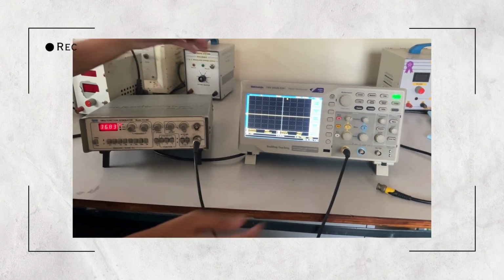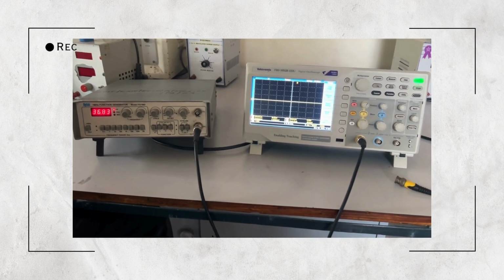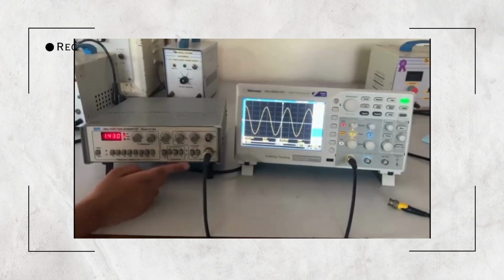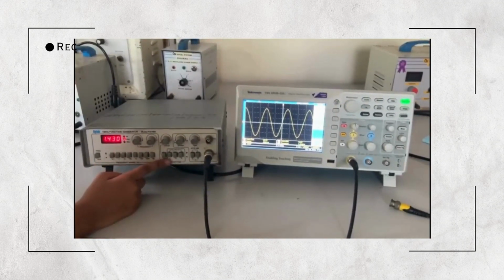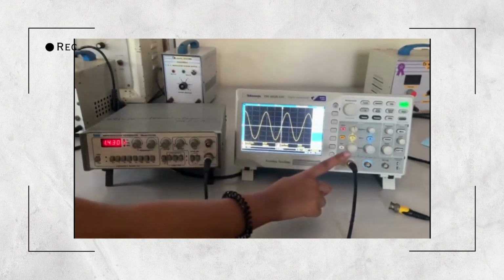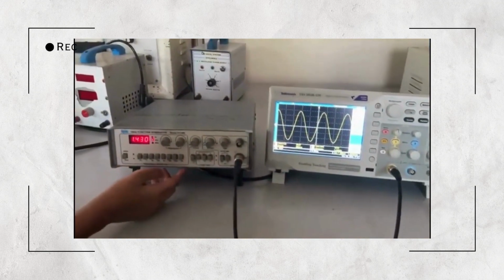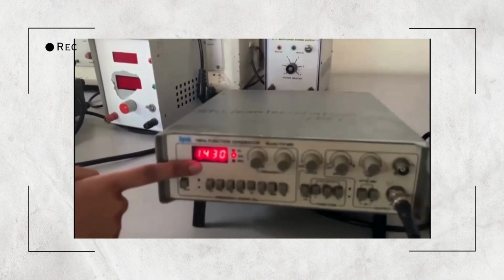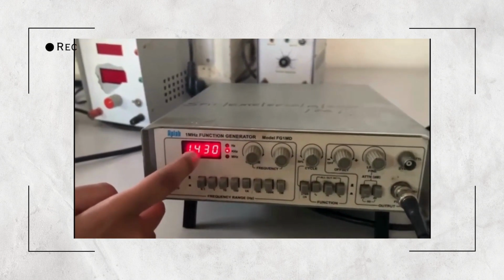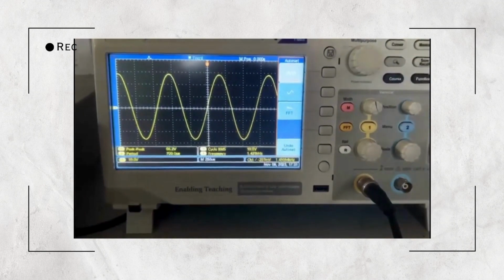Now we are connecting the probe from the function generator to the digital oscilloscope that is present over there in order to generate the signals. For visualizing the waveform, we need a DSO. That's why we have connected the probe from the function generator to the DSO to visualize the waveform. We have applied a frequency here, and that waveform we have to visualize on the DSO. Here we can see a sinusoidal waveform that we have applied.